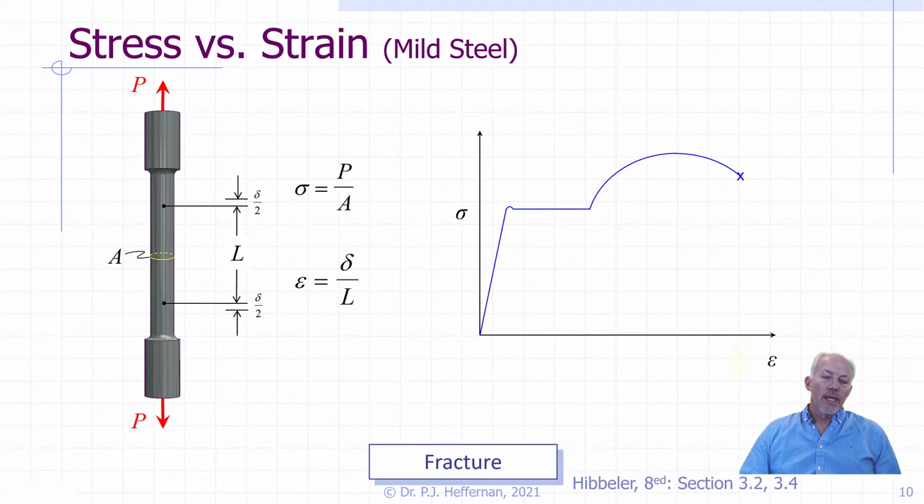The fracture point. So this is the point of fracture. While it appears as if the load is dropped off, this is simply because we are using the original area for the calculation. As a result of Poisson's ratio, the area of the cross-section is actually reducing as the bar gets loaded. This is negligible for our purposes. If, however, we were to divide by the instantaneous area, we would get the true stress and strain, and it would plot as shown.